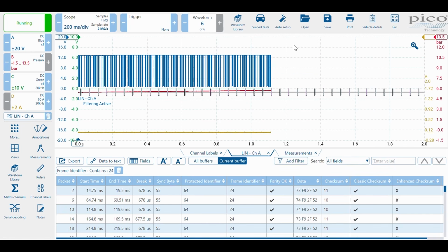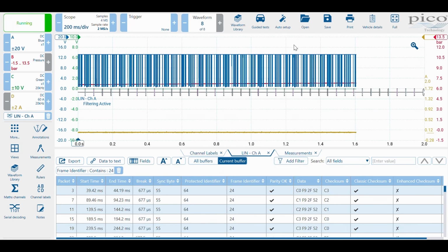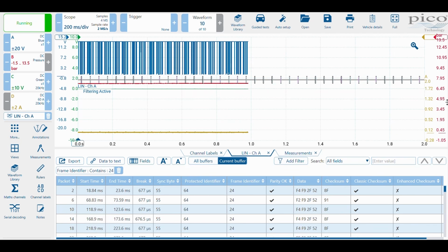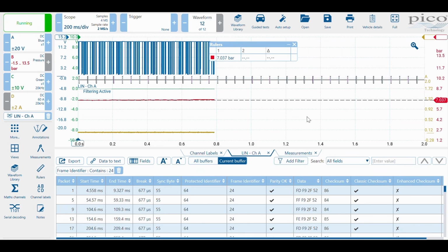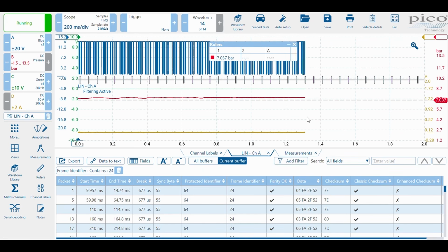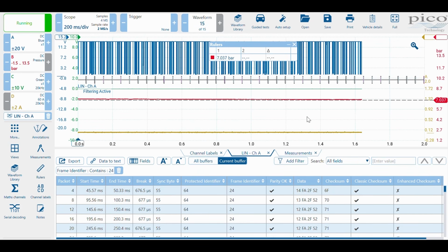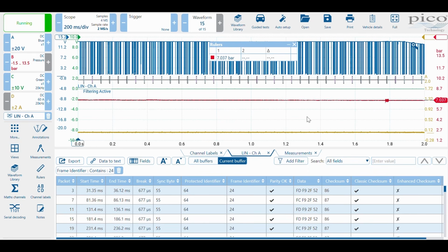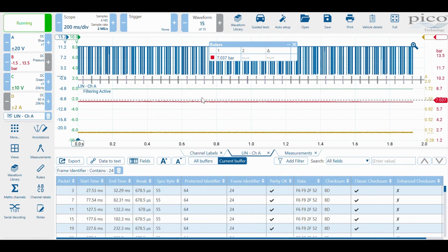So ready mode is on, air conditioning is on, and we should be seeing an increase in pressure. We're seeing it climb up there. If I just bring this down a little bit, we can see there that our pressure is now at 7 bar and quite stable as well, climbing still. A tip here then, we want to get a portion of pressure where there is no change. So if we've got ripples in our pressure, if we now turn the air conditioning off, so ignition is now off, we'll see that falling steadily.